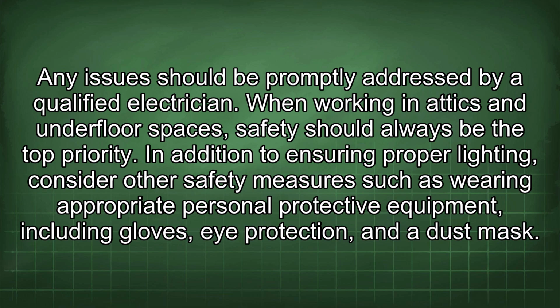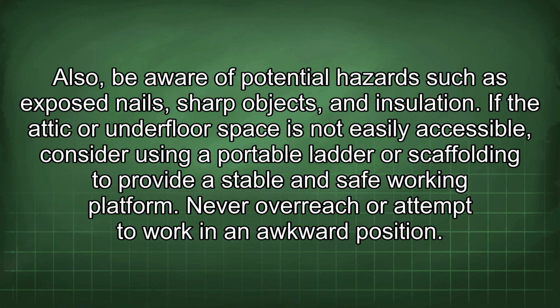When working in attics and underfloor spaces, safety should always be the top priority. In addition to ensuring proper lighting, consider other safety measures such as wearing appropriate personal protective equipment, including gloves, eye protection, and a dust mask. Also, be aware of potential hazards such as exposed nails, sharp objects, and insulation. If the attic or underfloor space is not easily accessible, consider using a portable ladder or scaffolding to provide a stable and safe working platform. Never overreach or attempt to work in an awkward position.